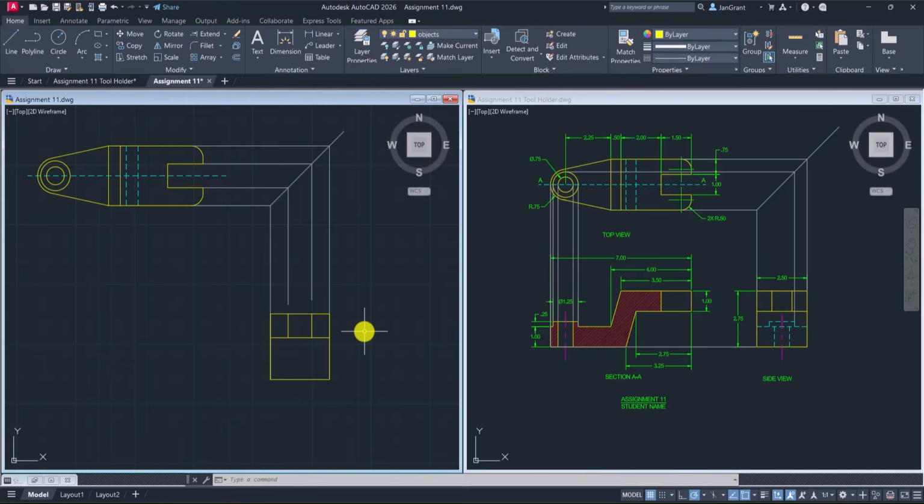But now it does make it a little bit easier, I think, for us to create these hidden lines. Although we could use offsets here and the diameters for these circles to draw the same side view, I think it might be a little helpful to use the miter method of drafting.